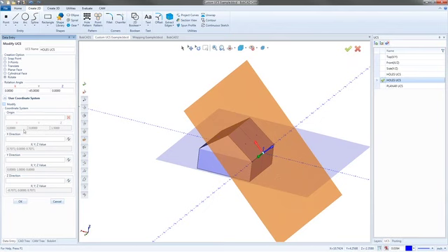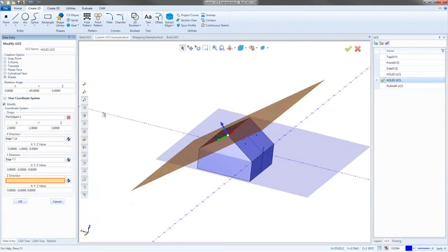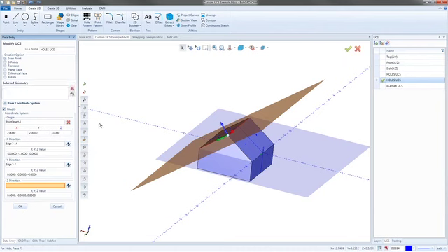And then your user coordinate system down here actually allows you to modify the coordinate system based on where the origin is. So I can move it around based on that. I could also tell it the direction. So I could say that my X direction is actually going this way and my Y direction is actually going this way. And that's just going to flip it around. So just like the 3 points, but without actually doing anything. If you left it on the snap point function and you just click the modify tab, you can go in and define everything about that UCS really without working too hard. So you just have to go pick lines that represent the X, the Y, and the Z.